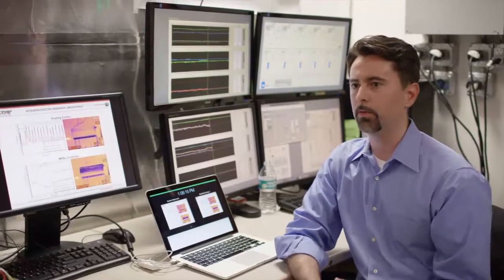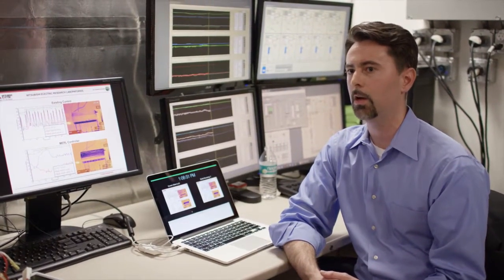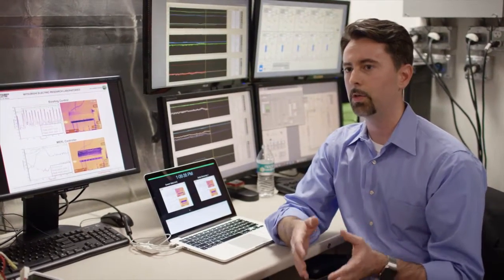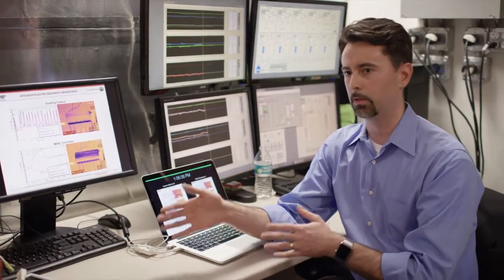This is a laboratory that we've built to understand the transient performance of air conditioners. Most labs in the world are built mostly to understand the steady state performance of air conditioners. We've built this lab specifically to test transients or dynamics of air conditioners, and that allows us to build dynamic models of the air conditioner, and we use those models to develop model-based controllers.